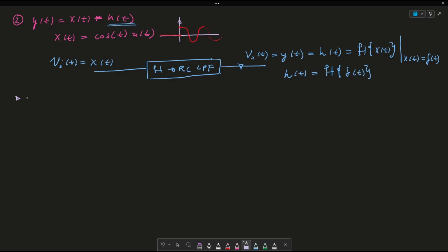All right, so now what we say is that since we're looking for the impulse response, the system must start at a 0 state history before the impulse strikes. So basically we're saying that imagine this x is this impulse. So 0 all the way until it shoots up here towards infinity, and then 0 after 0, where again this here is t. So as a result, we can confidently say then that V out of 0, or my initial condition, is equated to 0.